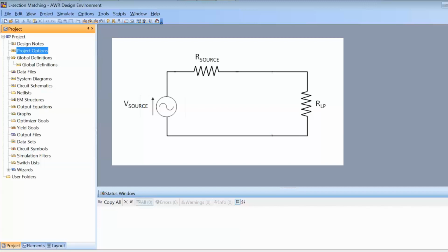So the first step towards this is to put a capacitor in parallel with it, because this way we will have additional current drawn from the signal generator, which will be used to charge up the capacitor, and hence the overall current which flows through the parallel of the capacitor and the resistor will increase. However, the amplitude of the voltage that we have across the parallel will be the same as the one that we had across the resistor.